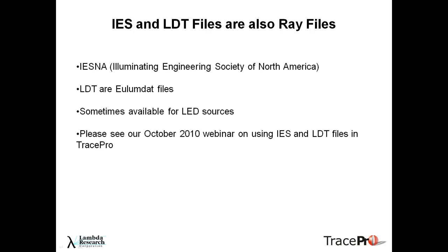Now, I mentioned briefly IES and LDT files. Well, these are also ray files. IES is the Illuminating Engineering Society of North America, and LDT is a file format most commonly used in Europe, short for IllumDat files. Both of these are ways of transferring photometric data, so angular positions and candela values.